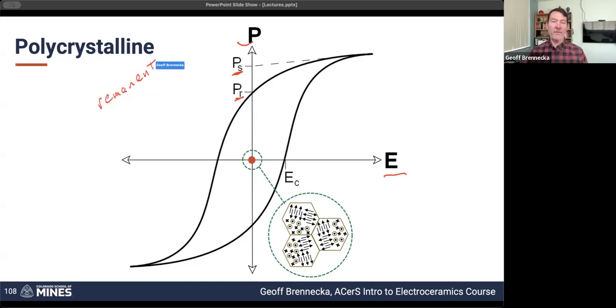And so you'll notice that's kind of a funny spelling. That is the IEEE convention, the standard spelling for remaining polarization or remaining magnetization after having removed a field. In colloquial English, it's remnant with no A. According to IEEE, we have to add the A in there when we're talking about polarization or magnetization, and so it becomes remanent. I didn't get to choose it, but it's an easy way to tell whether someone is familiar with the field or not if they use the English version or the IEEE version.